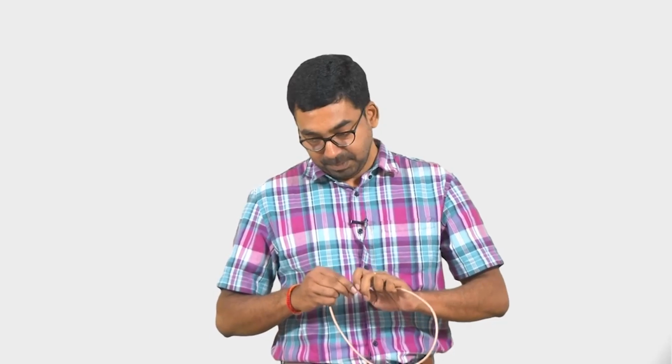Specifically, it is a kind of transmission line. This particular one is a coaxial cable, and there are many kinds of coaxial cable that you can find in the market. This is just one version of them. It has a conductor in the center and a conductor around it. It is a straight conductor in the center and then a braided conductor around it, and the ends have some kind of connector. These are SMA connectors, sub-miniature version A, that can go into some devices which can probe RF.